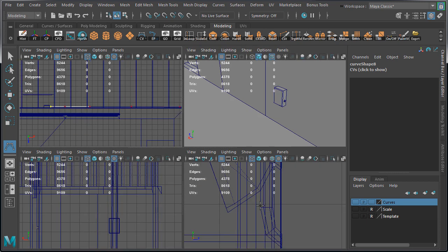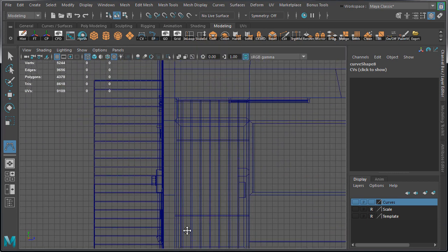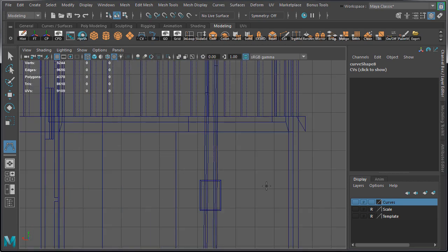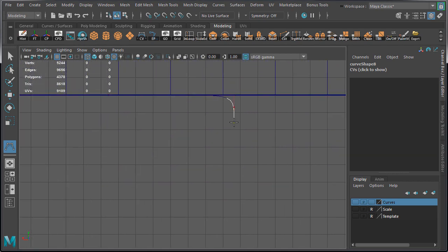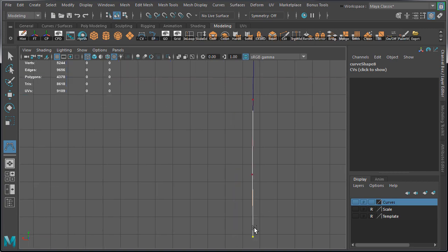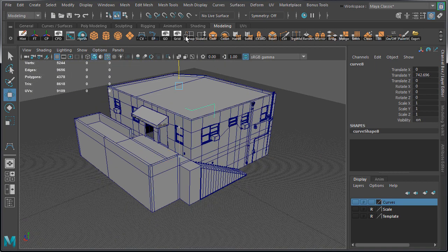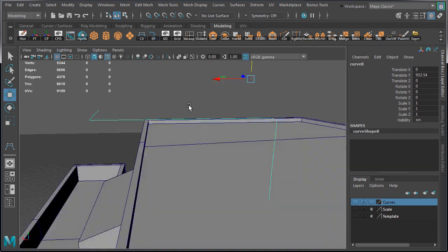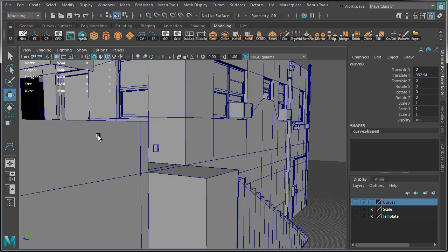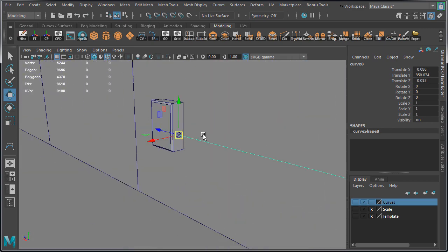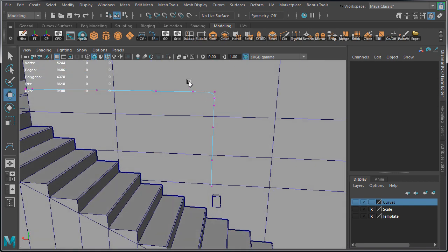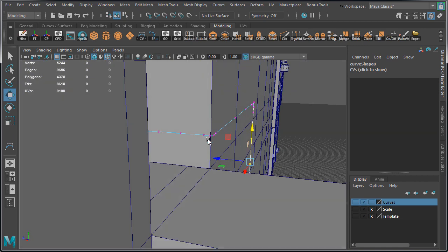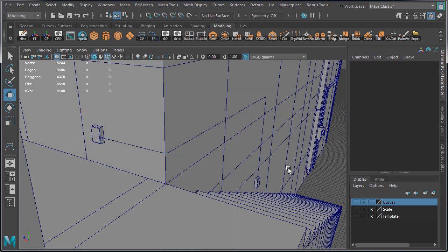And to do this, we first create the curve in top view, and when the curve changes directions to go down the wall, we need to switch over to side view. And since the curve is always created on the grid, we have to continue creating our curve without looking how far it needs to extend down. So I just added a bunch of control vertices going down, and then we repeat the same steps by moving the curve up and modifying control vertices more accurately.